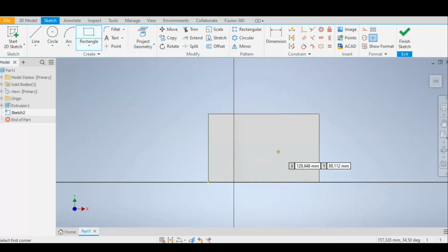So this, then again, you can then select this from a coordinate based system where your center point will be there, would be 0 there, but then you can do coordinates if you would like to, or you can simply select somewhere onto your sketch and change your dimensions from there.